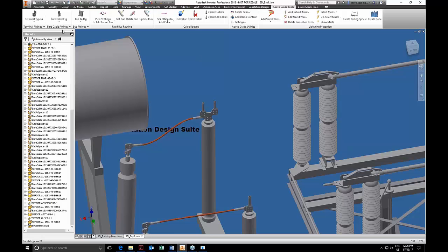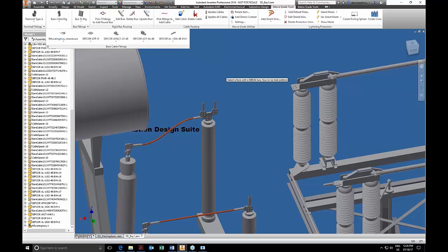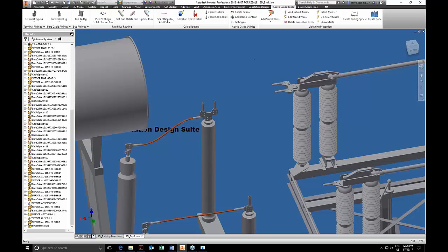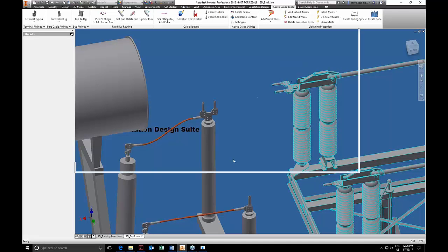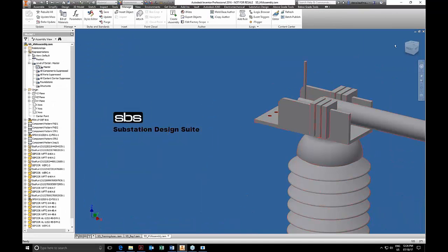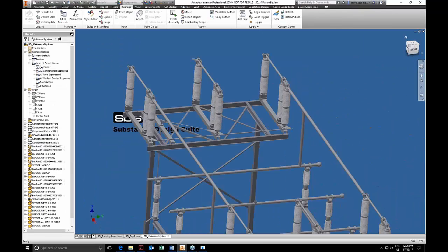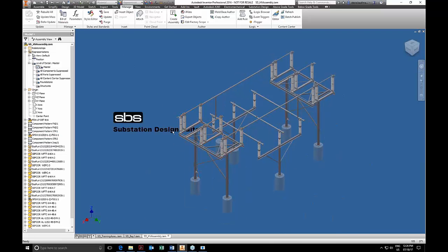Now we're going to add that piece again here. So now we have the two assemblies we've added here. That's part of the high side now, because that's what we want. If you take the course, you know we want everything populated on the islands as much as we can. This is an island because it's all rigid bus. We want this to move vertically with the slope of the land all together by itself without having to try and change individual pieces, as well as it helps us for levels of detail.